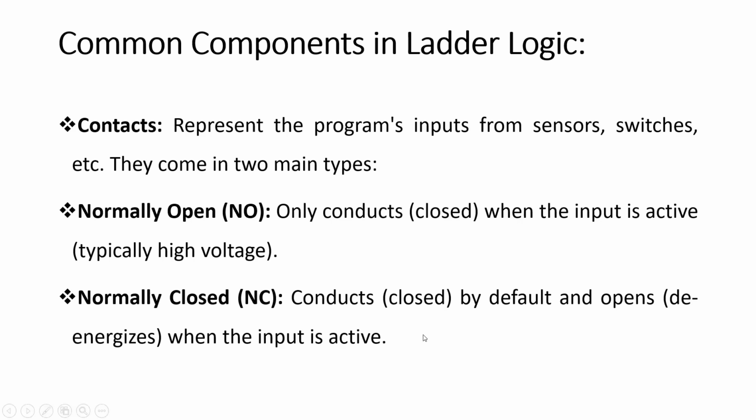So when the input is active, it de-energizes and opens the contacts, and then you are able to either stop or start the system, depending on the configuration or the design that you use.